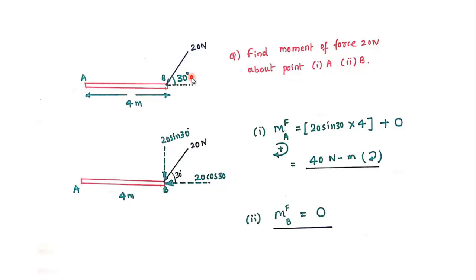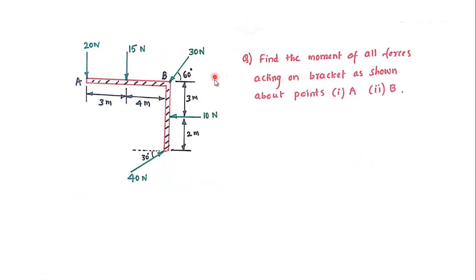Okay, now what we are going to take from here is that whenever forces are coming at a certain angle, we are going to split them into vertical and horizontal components, and then we will calculate the moment.